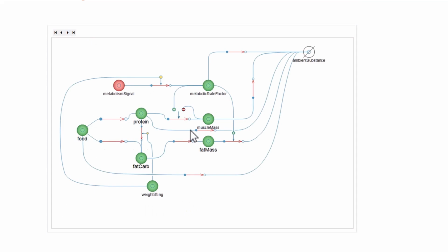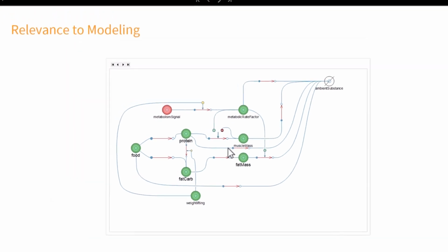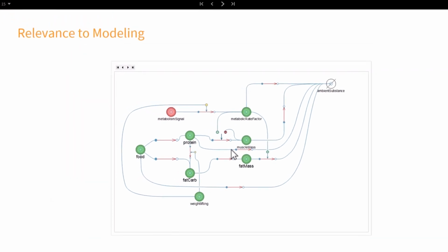Finally, starting simple helps you in understanding your system. A simpler model with a smaller number of parameters would allow you to use model calibration, test uncertainties in parameters, and check sensitivities. As you create a more detailed model, doing such analysis becomes very computationally expensive and might fail in unexpected ways.